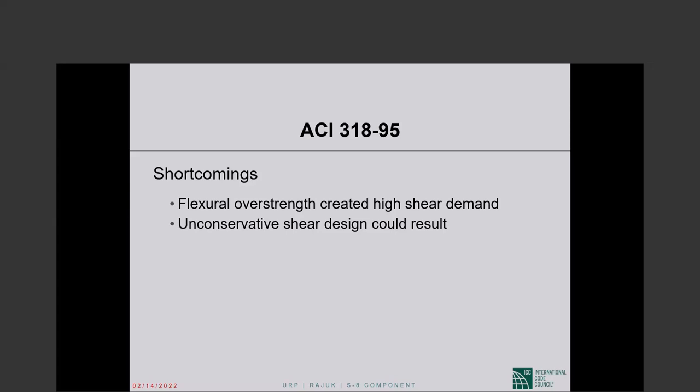When we do the shear design of this shear wall, we do not consider that fact. You saw yourself, V sub u comes from analysis of the structure under code prescribed seismic forces. It doesn't even consider whether the wall is over strength or under strength. So brittle shear failure of the shear wall was highly likely.